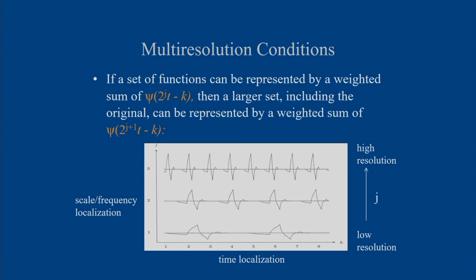And now I will discuss the concept of the multi-resolution analysis, how to analyze a particular signal in different resolutions. So suppose a set of functions can be represented by a weighted sum of this basis function, the function is psi 2 to the power j t minus k.